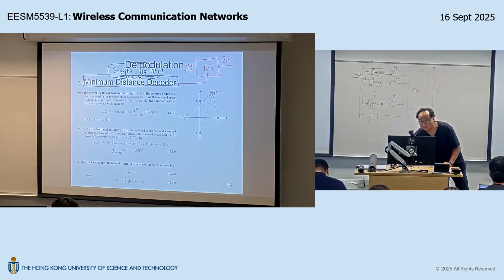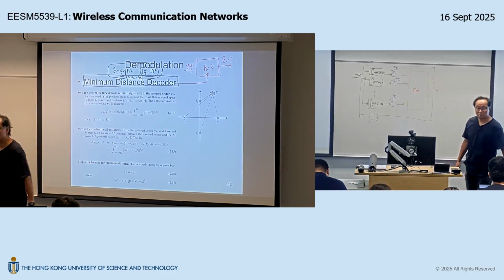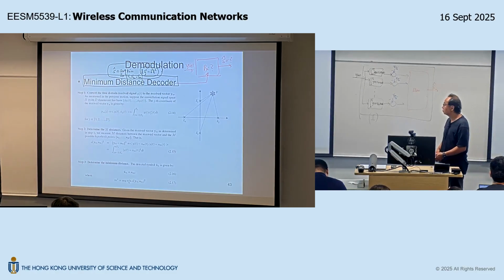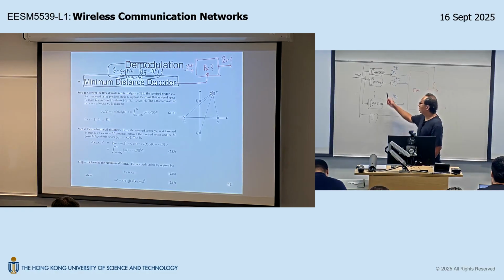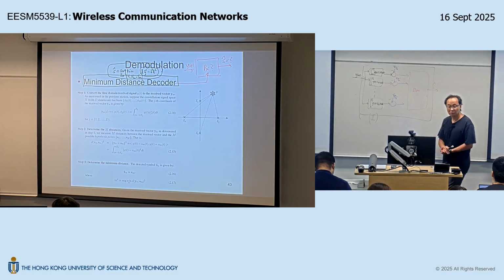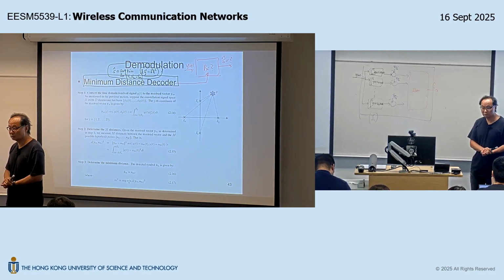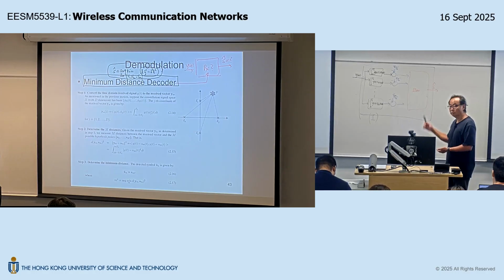This is the algorithm. So they will have the same performance. They may have different implementation costs. For example, this one requires M correlators. The first one only requires 2 correlators. Is that okay? So they may have different cost considerations, but they will have the same performance.